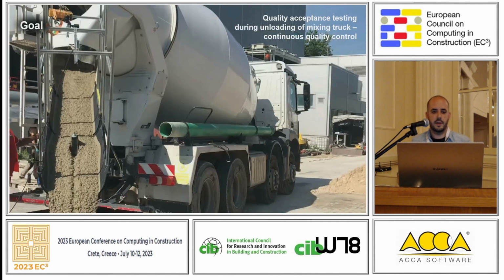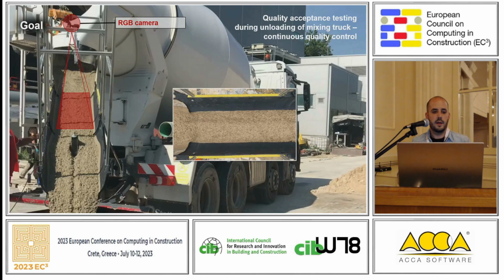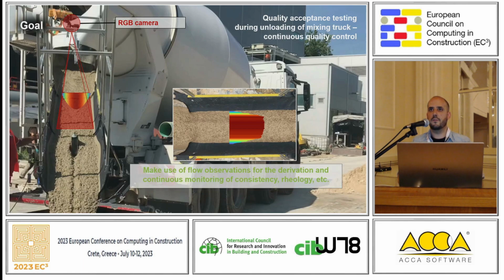So what we therefore propose in our work is to measure and predict the workability of the concrete directly at the delivery by observing the concrete flowing at the discharge of the mixing truck. And for this we installed cameras on top of the concrete channel, observing the concrete flow, and by computing the motion of the concrete, we assume that we have all the relevant information that we need to derive the fresh concrete properties.